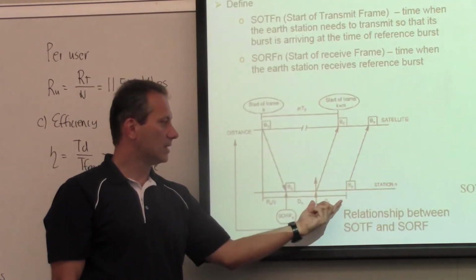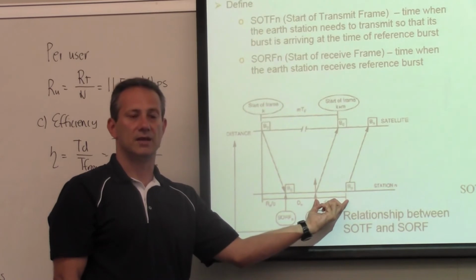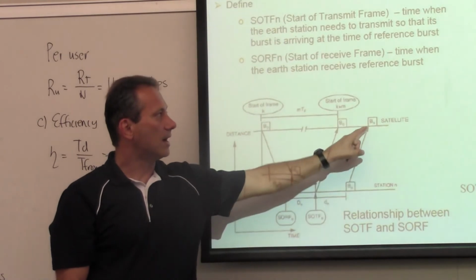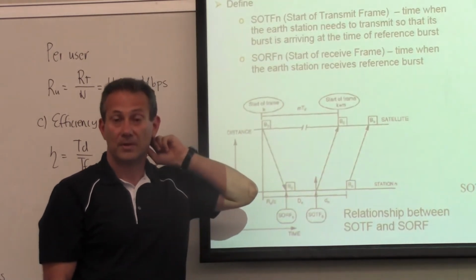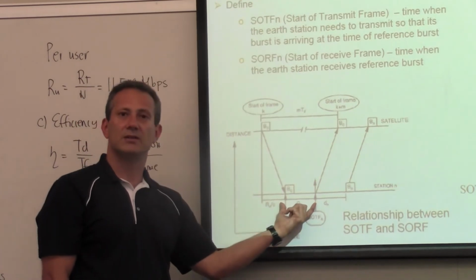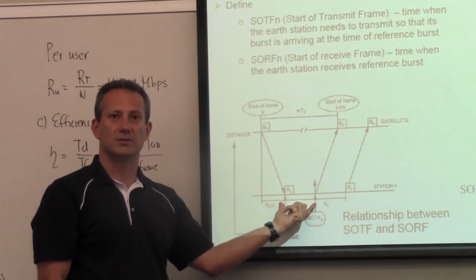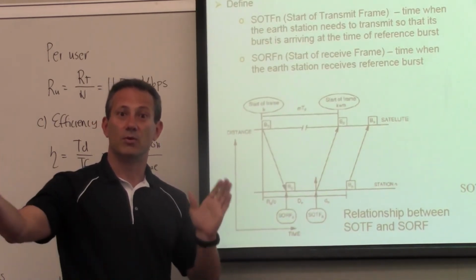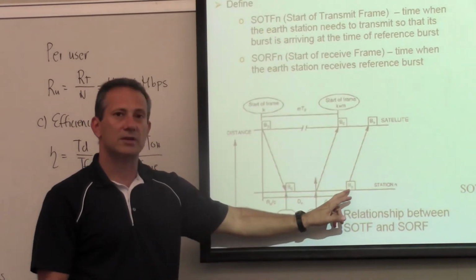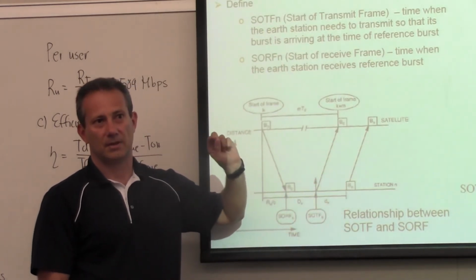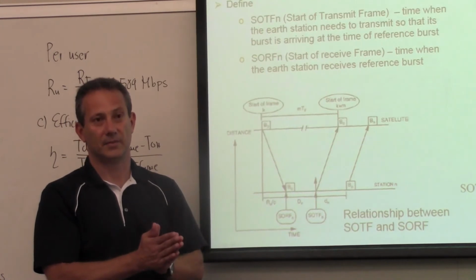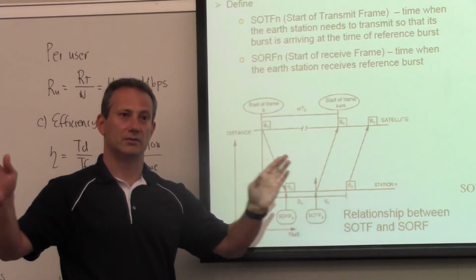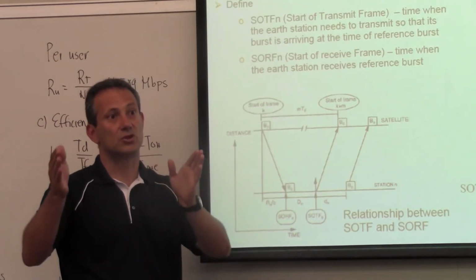And then on top of that, I'm going to delay by dn. That's the n times the duration of the time slot. And then if I transmit here, I'm going to fall within an appropriate slot. The weak part here is my estimate of dn, right? That's a ballpark estimate. So at this point, I cannot be that courageous to just transmit with a full burst. What I'm going to do is transmit just my preamble, right? I'm just going to transmit the preamble and leave the data out for now. This is what sometimes is referred to as shortened burst.